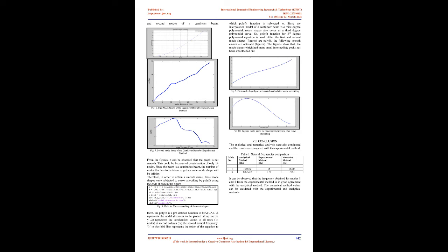The frequency domain data for all 14 nodes is acquired and stored as separate files in the system. Post-processing in MATLAB: the frequency response curve for each node of the beam is obtained by plotting a graph of frequency and acceleration data, with acceleration on the y-axis and frequency on the x-axis. The graphs show the frequency response curve for the 13th and 14th nodes.